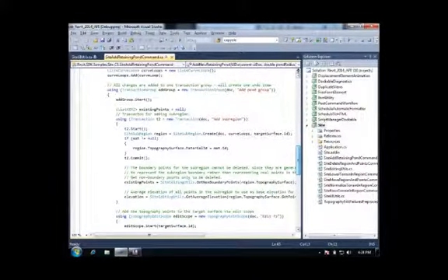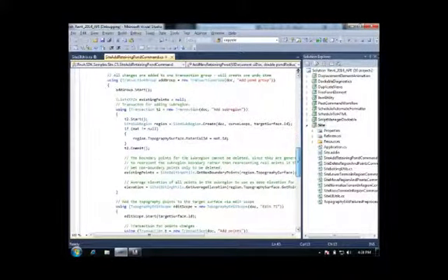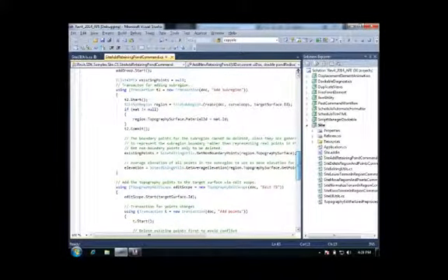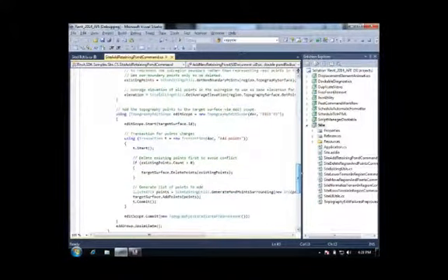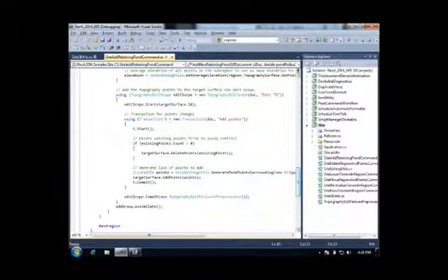And then we encapsulate the whole database modification in a transaction group. And the first transaction is implemented to add a subregion. The second one is editing this region, which requires a topography edit scope and a new transaction to add the points. And here you can see how the edit scope is committed and started just like a transaction.